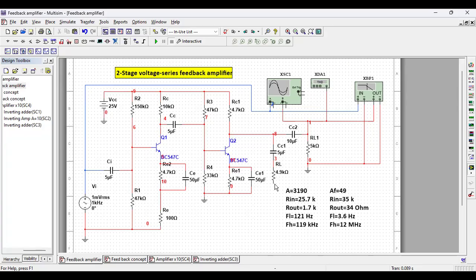Now, the feedback circuit point is connected here. Look at this now. If this point is connected here, then what happens? This is the output of the second stage, and it is connected to the load of 5 kilo ohm resistance. From here, see, there is a 4.9K resistor and a 100 ohm resistor. So total is 5K resistor. This is also a 5K resistor, right?